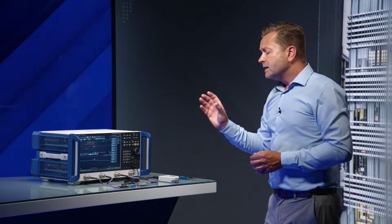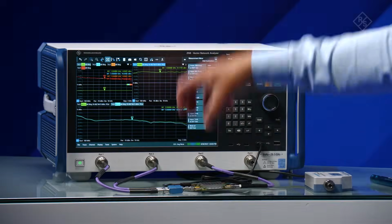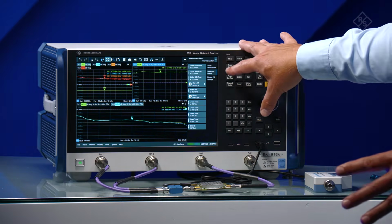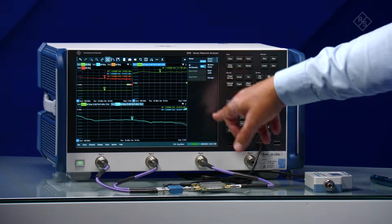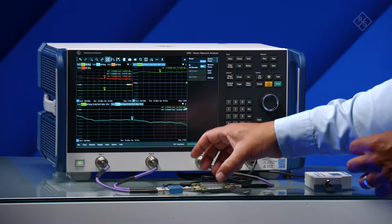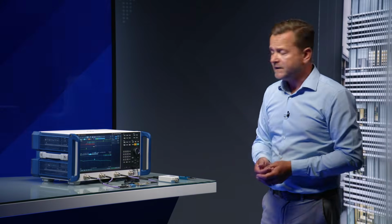Now with any of these active device measurements, we need to be absolutely sure what we measure is coming from the device under test and not coming from any nonlinearities in our receiver. If my network analyzer has step attenuators built into the receiver on the port, then in the power menu, I will see those here. This particular one does not, but I've already verified that what I see here is coming from the device and not from the receiver. I could, if necessary, add external attenuation and calibrate that out.